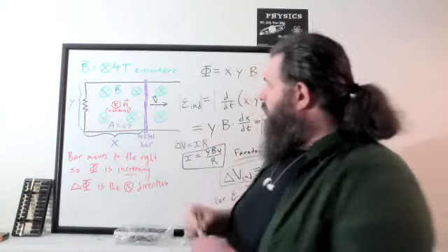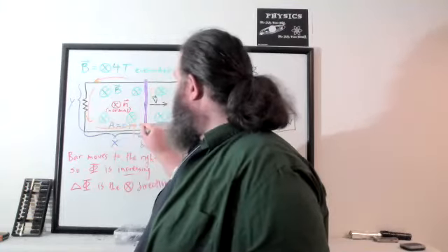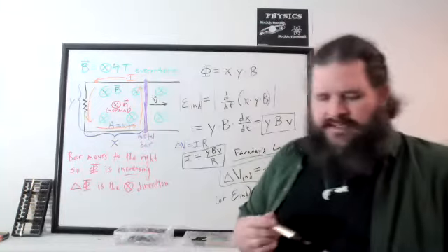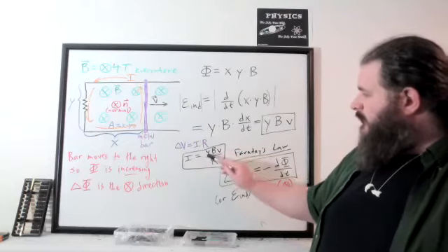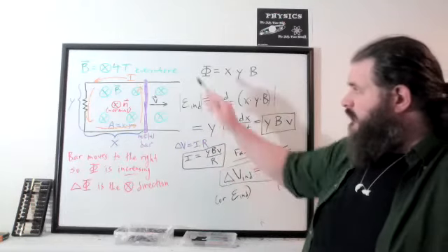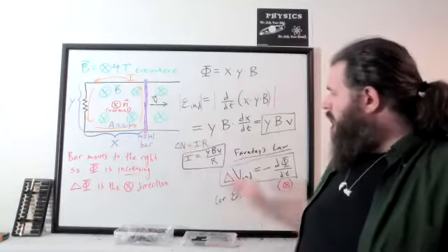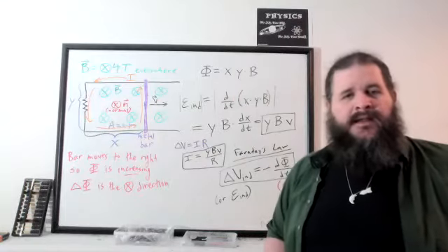As the bar moves to the right, we get current flowing counterclockwise. And we can even calculate how fast that current is. That current will be distance between wires times 4 teslas, the strength of the magnetic field, times the speed of that bar, divided by the resistance of this light bulb or buzzer or whatever.